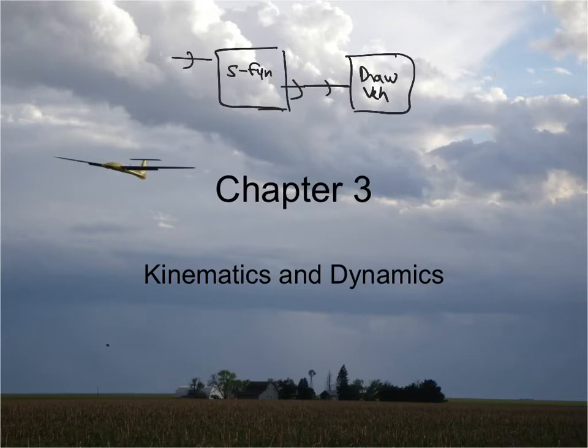For now, we will just focus on the fact that there are some forces coming, Fx, Fy, Fz, all of them in body frame, and torques L, M, N. So this block will take 6 inputs: forces in the forward direction, sideways, and up and down, all in body frame, and then torques. You have a torque to rotate the vehicle about the x-axis, a torque to rotate it about the y-axis, and a torque to rotate it about the z-axis. So 6 total inputs to the system.